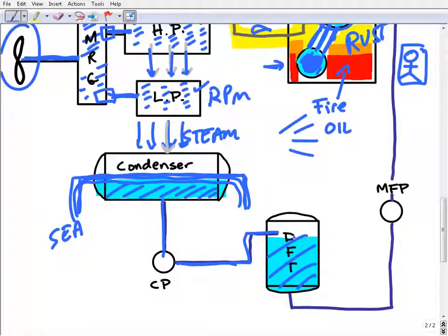But the deaerating part is a reference to taking the air out of it, and that's one of the main reasons for the rusting. So deaerating is taking out any oxygen that we picked up during this process. I'm not going to get into it too much, but essentially this condensate gets splashed in this tank. We push it through with splashes, essentially smashing water against the tank to knock out oxygen molecules, and then we have a pure form of the condensate down here.